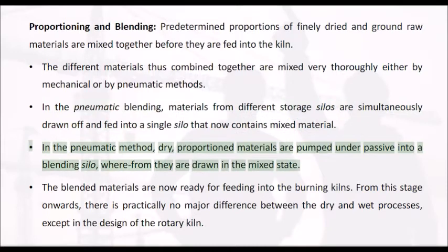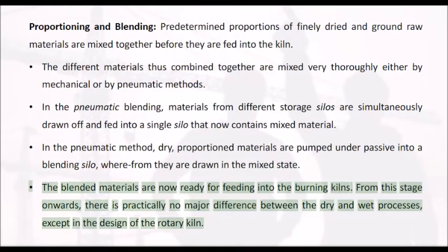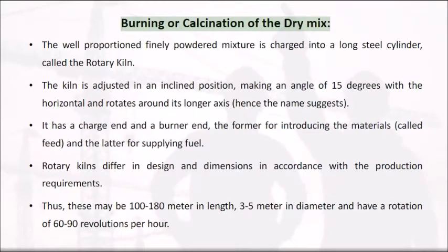In the pneumatic method, dry, proportioned materials are pumped under pressure into a blending silo, wherefrom they are drawn in the mixed state. The blended materials are now ready for feeding into the burning kilns. From this stage onwards, there is practically no major difference between the dry and wet processes, except in the design of the rotary kiln. Burning or calcination of the dry mix.